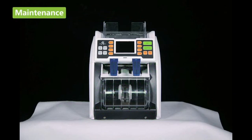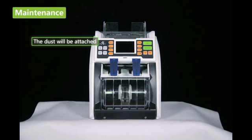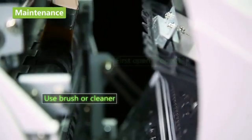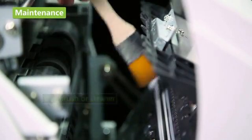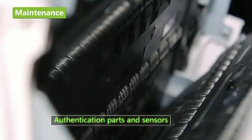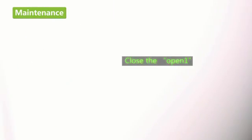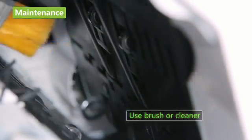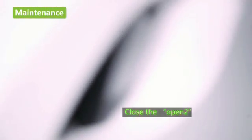Maintenance. After operating for a long time, dust will attach and cause movement errors. Please always clean. Attention! Turn off the power supply when cleaning and opening the machine. First, open 1. Use a brush or cleaner to clean the dust on the transmission mechanism, authentication port and sensors. Close open 1 after cleaning. Then open 2. Use a brush or cleaner to clean the dust on the transmission wheel and around it. Close open 2 after cleaning.